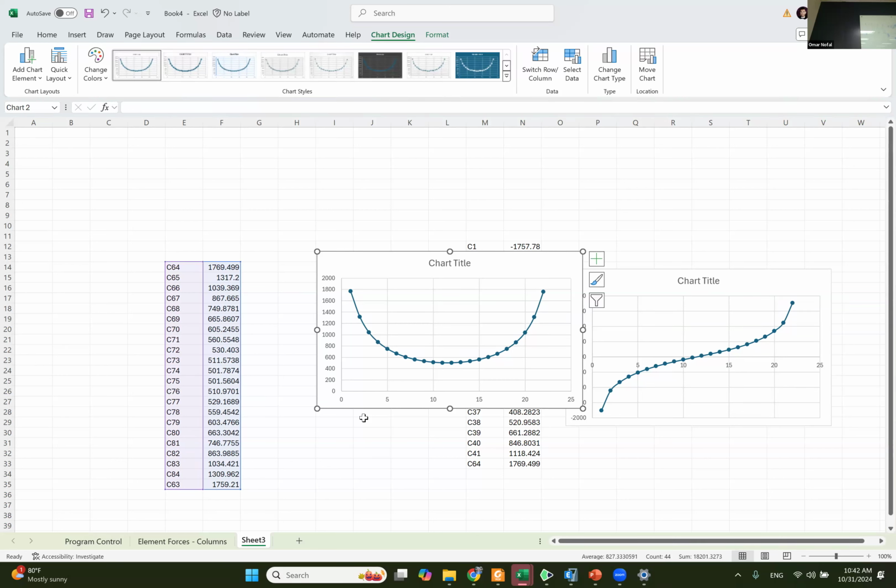Because I want you to do the same thing at different stories, like we did at the basic story, try to do it at the 10th story. And maybe at the 40th story, maybe 3 or 4 of them. And see how it's going to look, because this is going to be different. The shear lag is getting less, even at some story it becomes almost 0. Except the corner columns, because the corner columns are always stressed.